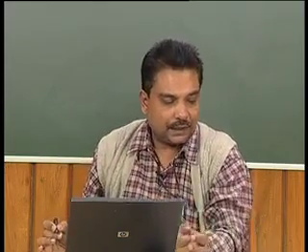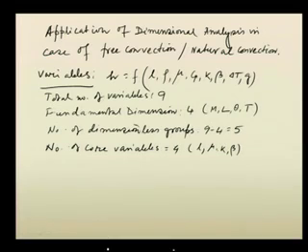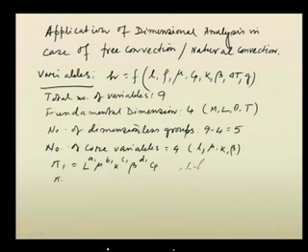Now, we will list that there should be 5 dimensionless groups. Let us assume these 5 are pi 1, that is L to the power a1, mu to the power b1, k to the power c1, beta to the power d1, and then one variable added to the core group, that is Cp. Similarly, pi 2 will be L to the power a2, mu to the power b2, k to the power c2, beta to the power d2, and another variable, rho, is placed over here.